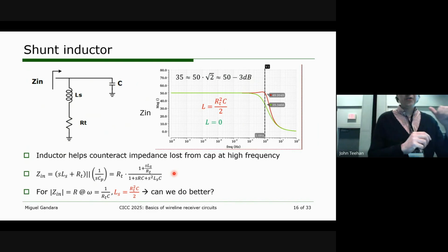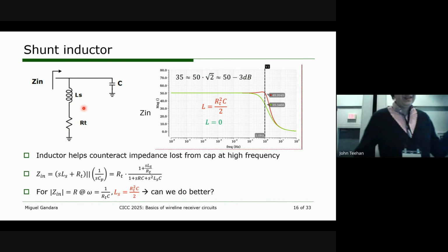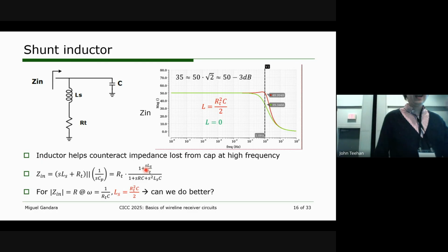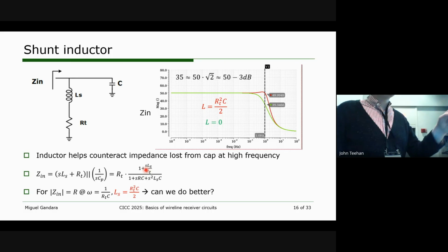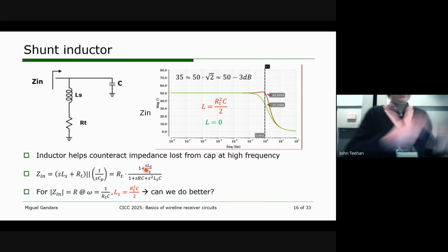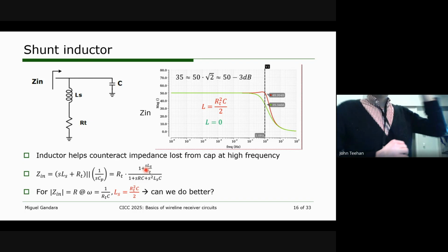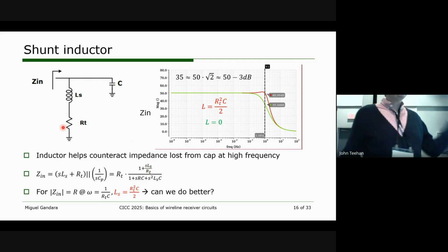Okay, so the first point I want to make is that in the numerator, we have a 0. As I mentioned, this 0 comes from the fact that we have increasing impedance along with the inductance, okay? Now, the denominator is second order. That means that at high frequency, we're going to end up with an impedance very close to 0 because the order of the denominator is higher than the numerator. I can say that I knew that would be the case even before I did all the math here, okay? The reason is that we have this impedance, which increases with frequency, in parallel